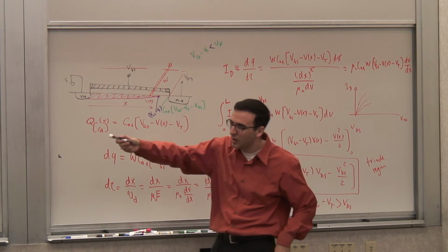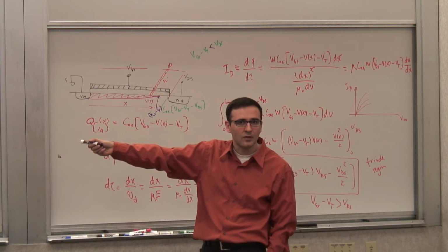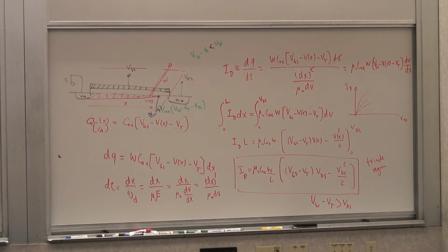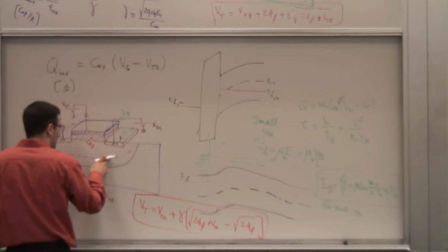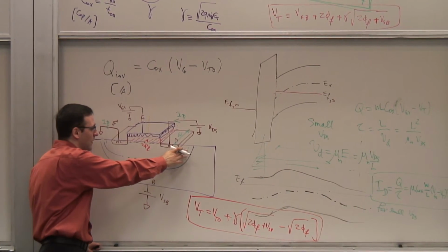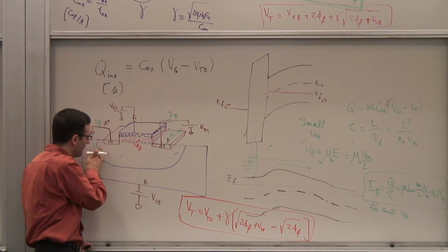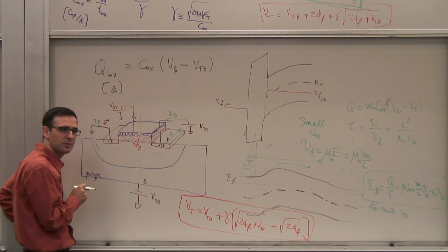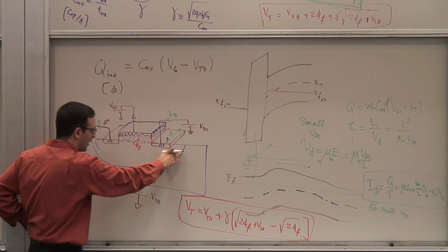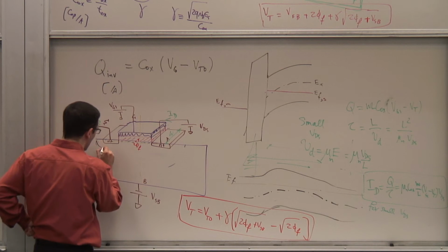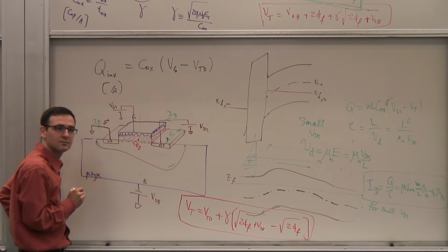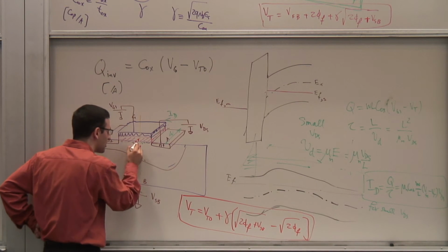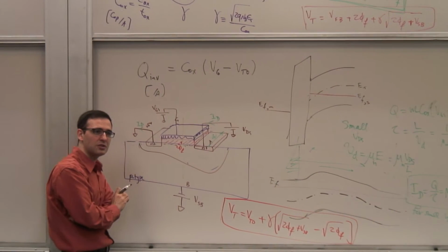Think about body effect, right? For each one of these little transistors, you see the depletion region. Originally I said the depletion region looked like this, right? So if I had no VDS, I had a kind of uniform depletion region underneath. But if I apply larger VDS, which side would have a larger depletion region? This side, right? Because you have more negative voltage. So it becomes like this. It becomes oblique. So at different places underneath the channel, I have different widths of the depletion region.